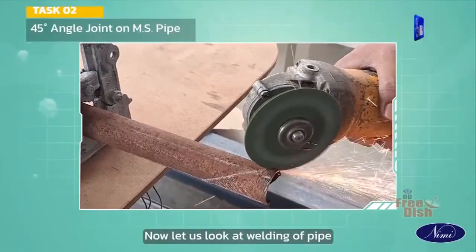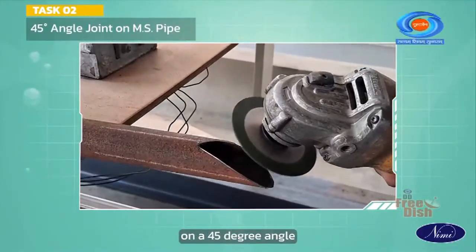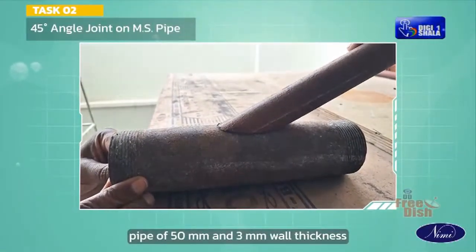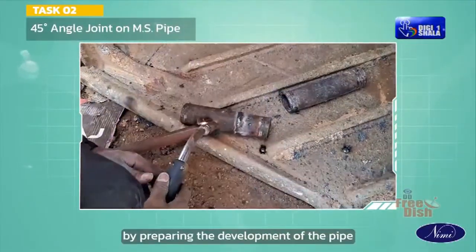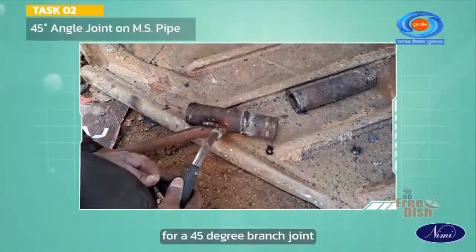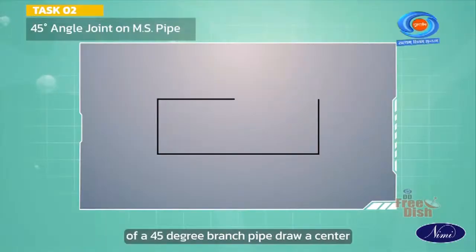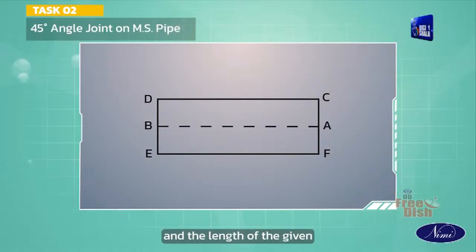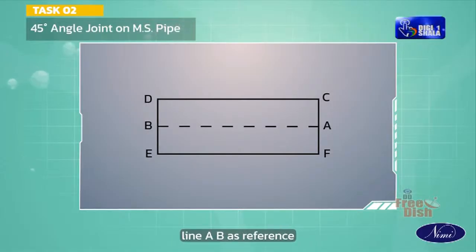Now, let us look at welding a pipe on a 45-degree angle joint on an MS pipe of 50 mm and 3 mm wall thickness by preparing the development of the pipe for a 45-degree branch joint. For the development of a 45-degree branch pipe, draw a center line AB. Mark the points C, D, E and F, taking the radius and the length of the given pipe using the center line AB as reference.